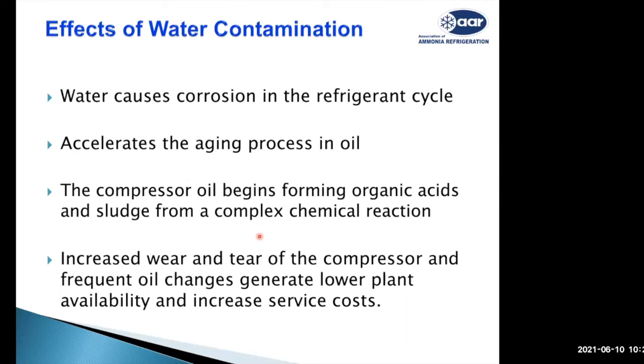You will need more oil changes, and more oil filters will need to be replaced, which will increase the plant running cost, the service cost, and also the shutdown cost for maintenance purposes, which means you need extra plant capacity or you will suffer in production.